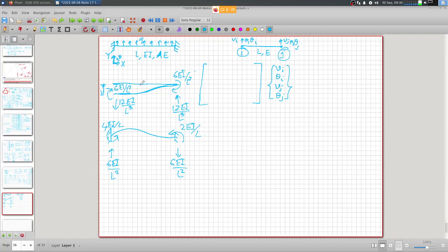These are the moments and shear force that you can relate to from your basic understanding of structural mechanics, right? So for sinking of supports, 1 degree of freedom Vi, if I impose unit displacement to Vi, and all other degrees of freedom, theta I, Vj and theta j, are restrained to zero, these are the forces that are acting, right? And that becomes the stiffness coefficients of this first column.